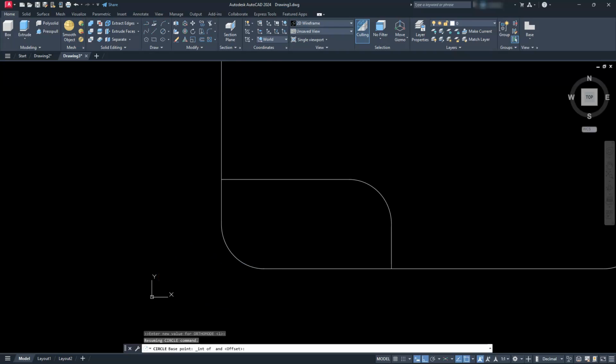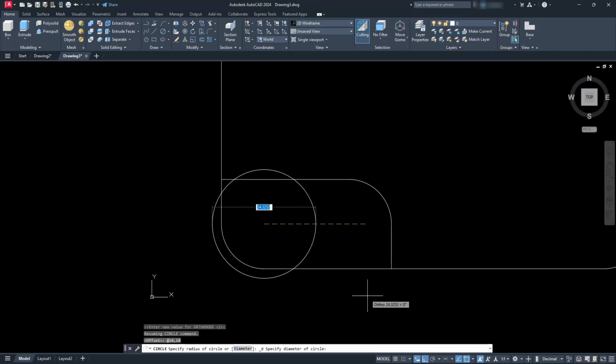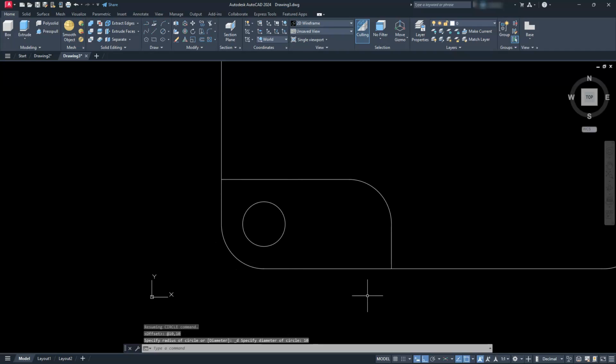You have to physically type in the at symbol, right? So I'm going to type in at 10, because I want to go 10 in the X direction, comma, 10 again, right? And it's going to go 10 in the Y direction. So once I hit enter, there it is. My circle is located. Last thing I need to do is go ahead and put in the diameter, which will be 10 as well. Okay, so real easy, some steps to go through.